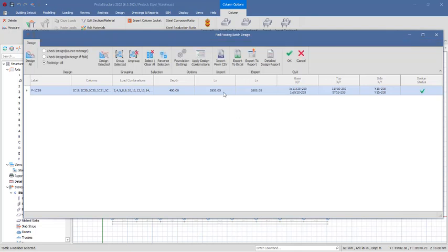So what are these footings? 1.8 by 1.8 by 2.6. That is quite a very large footing, and the depth of the footings is 400 right there, as you can see. That is one of the disadvantages of designing footings when they are being combined, because you may try to manipulate these sizes by, let's say, increasing this to